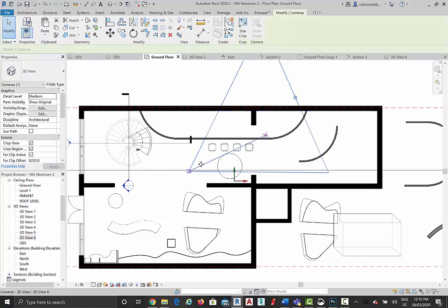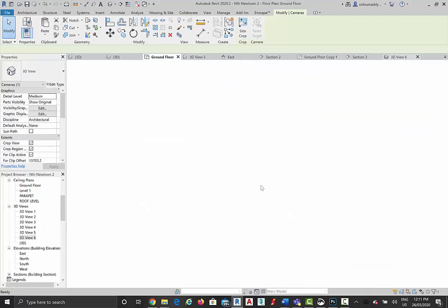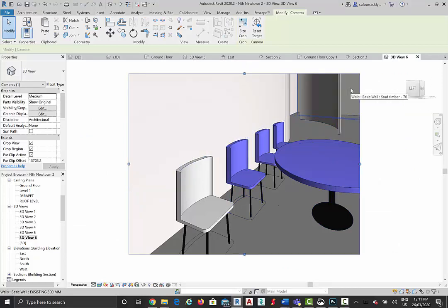That's a really helpful thing on its own. So being able to show the camera, if you don't know about that, is really important. It helps you to adjust them, of course, in Revit in different views. And so one option will be to drag the end of that view, that cone there. I can extend it all the way to include the walls. And then if I go back to my view, then I can see the walls that were missing. But that's only one option.